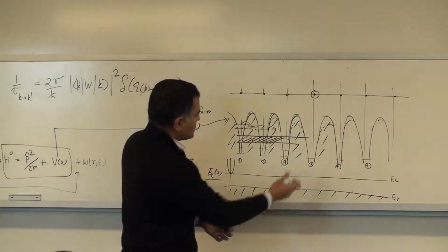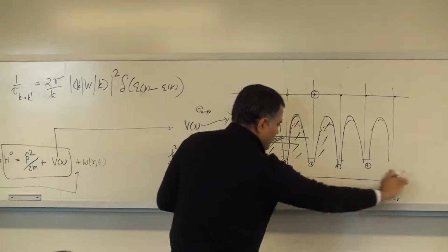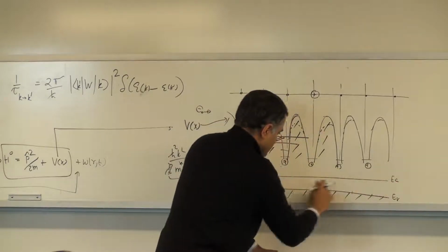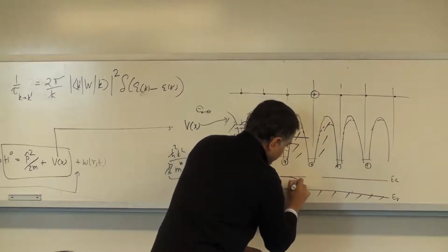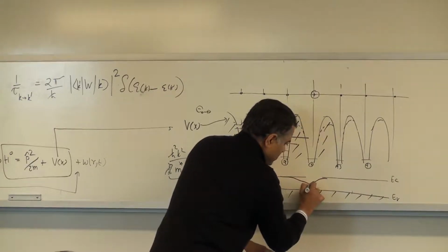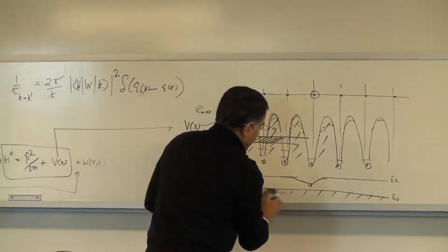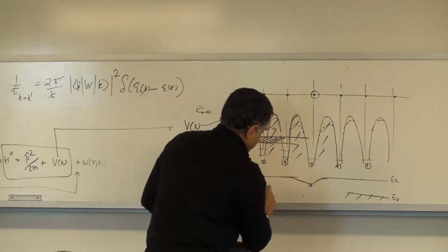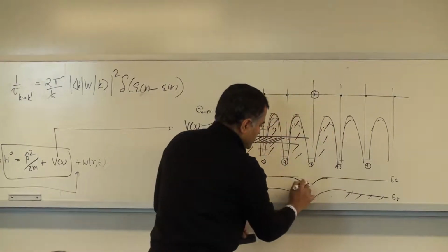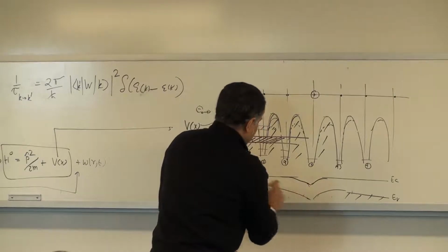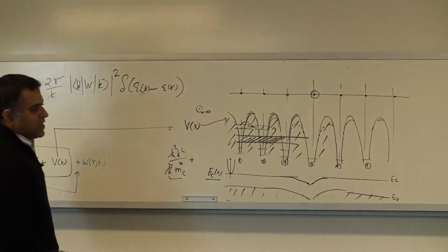Now, if I put a dopant or an impurity in this sort of mean field or averaged effective mass picture, what will happen is the conduction band will bend this way, and the whole thing will bend like that, right? The gap of the semiconductor does not change because of this, so the valence band will also bend a little bit like that. As a result, the electron will really be attracted to this point.